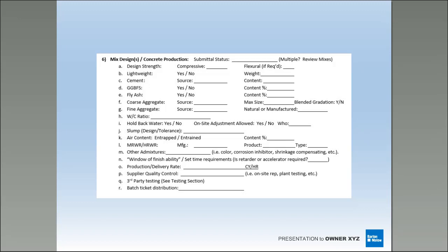of the mix he's going to be pouring, and he should supply that for every project, because you've got to have a break history on a mix design to show that it's been solidified, that it's going to work. So he's got to have some sort of history and testing on it. You want to get those breaks on the front end, because